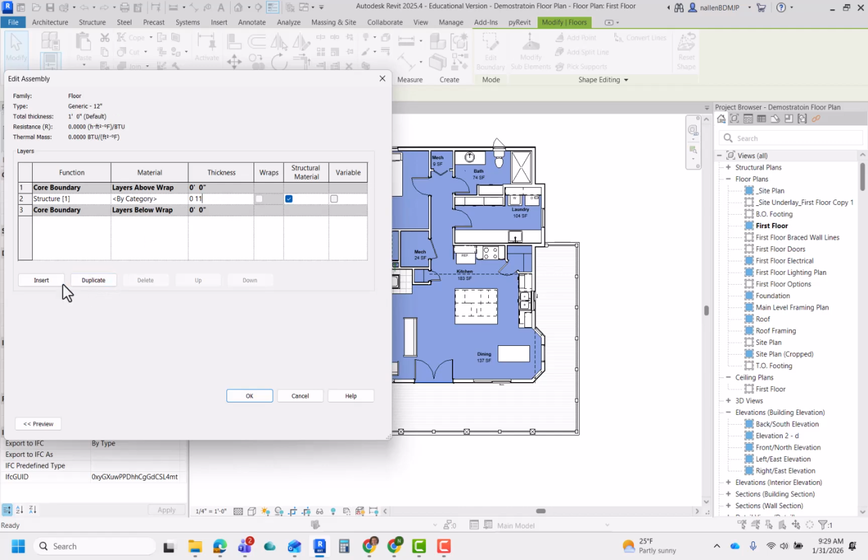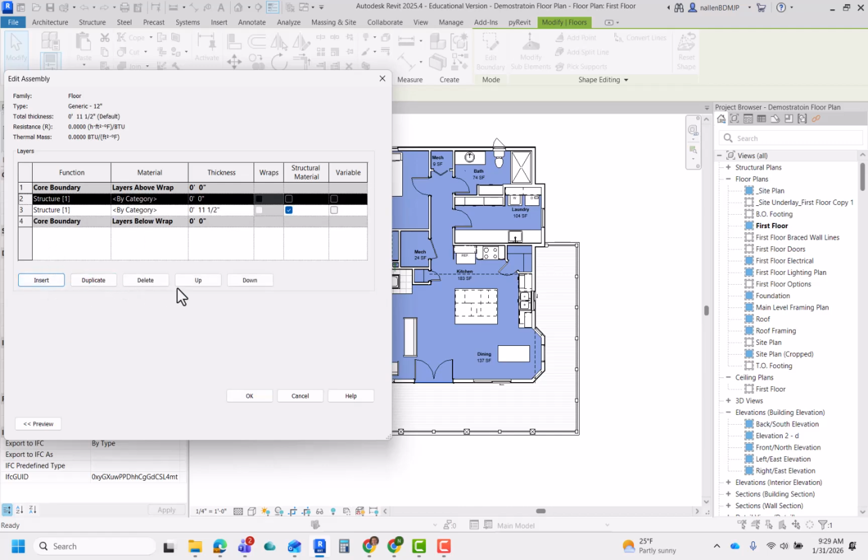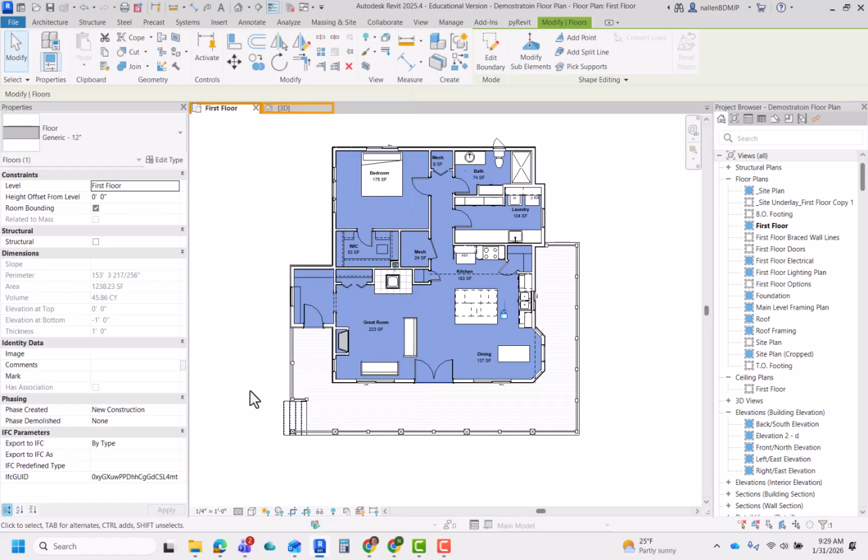And then the same thing that you saw on my deck, I want something on the outside of it, just at the top there. I'll make this 1/2 of an inch so that total I'm still 12 inches, 12-inch thickness for the whole floor. Okay, and then what will this material be? We'll apply another kind of a wood plank type floor. But before we do that, let's see what it looks like so far.